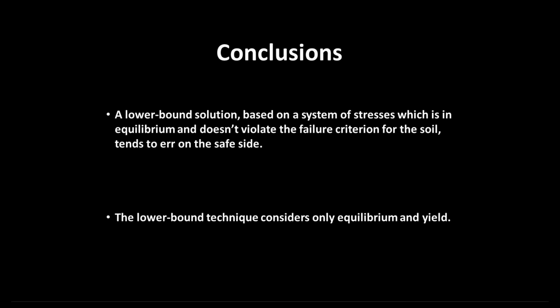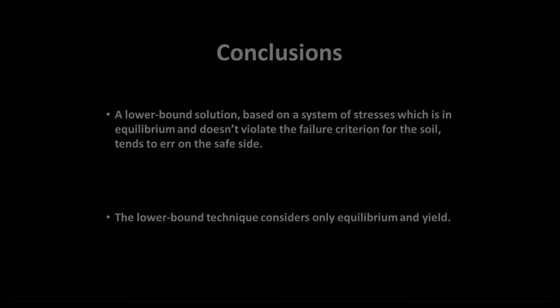From the conclusions, what did we learn? A lower bound solution, based on a system of stresses which is in equilibrium and doesn't violate the failure criterion for soil, tends to err on the safe side. The lower bound technique considers only equilibrium and yield.